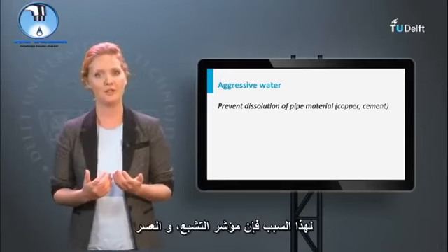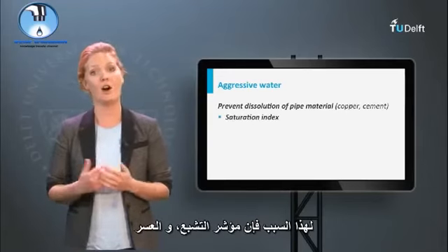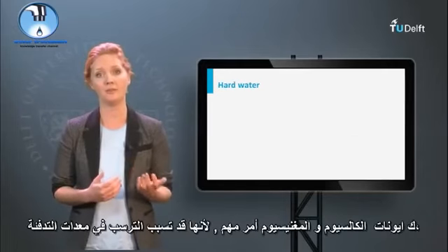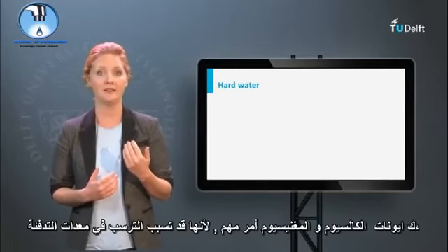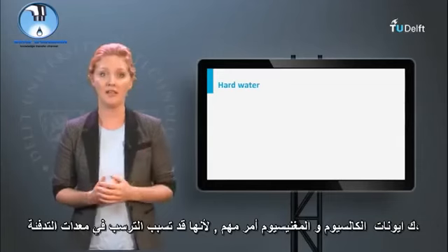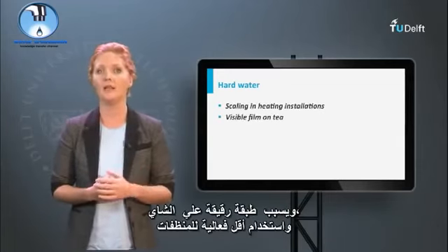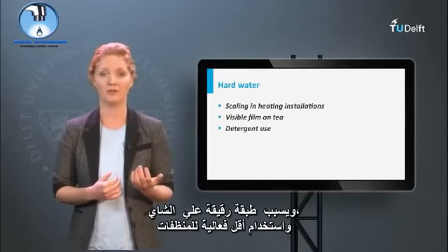For this reason, saturation index, hardness, and pH are important. But also the hardness of water, as calcium and magnesium ions, is important, as it may cause scaling in heating installations, a film on tea, and less effective use of detergents.